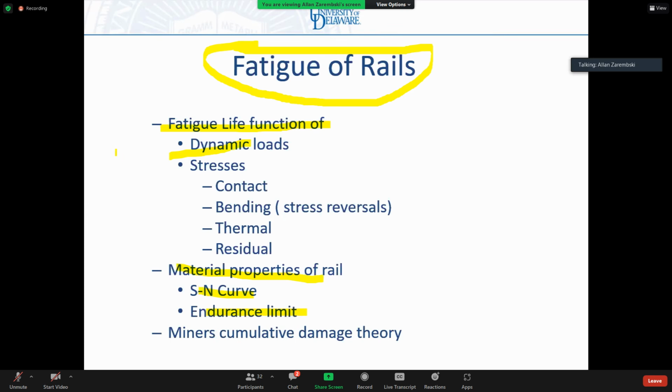One axle represents one loading cycle, because if you remember back from your beam and elastic foundation theory, things actually become useful at some point in time. If you look at, remember, your moment under one axle, I basically have a maximum moment here, I have a reverse moment here, and I go back to 0. So this is a loading cycle. So each axle represents one loading cycle.